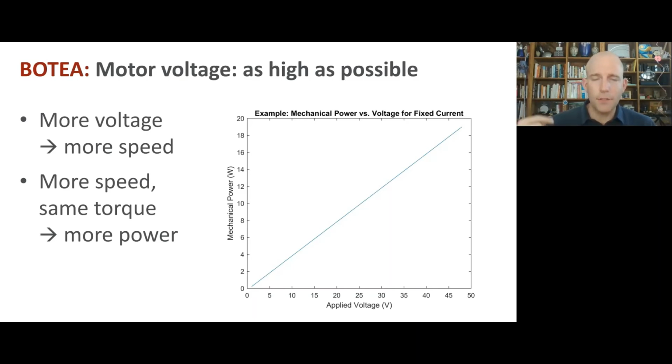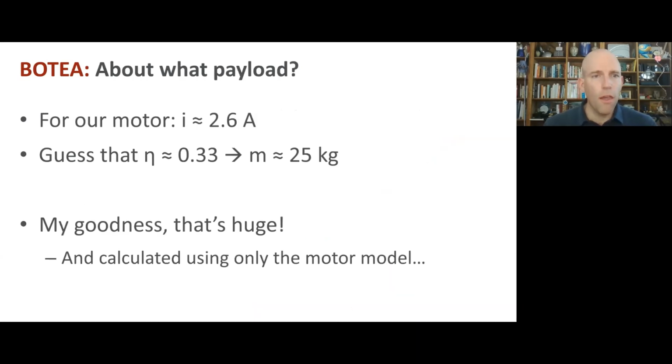As in, not too many cycles, around 12 volts with these motors. At higher voltages, we would have problems with our power supply. Eventually, in hundreds of volts, we'd start to maybe break down the insulation of our motors, or break down the transistors in our electric commutation for, say, a brushless DC motor. But for whatever system we have, within the practical constraints, we probably want to operate it at as high a voltage as we can. So what does that mean for our payload?